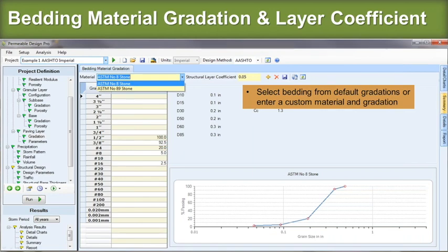It's smaller particles, 90% or so is 3/8 of an inch or minus. So they're fairly small. We don't want them to be too big, and we do want a little bit of gradation with them because we want them to be the bedding and to go in the joint material, because we need to have load transfer between the pavers. So we need to have shear capacity.